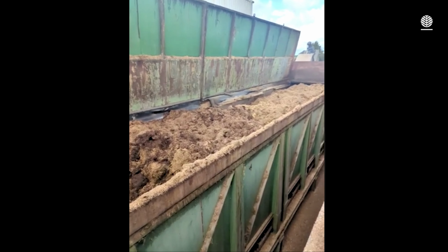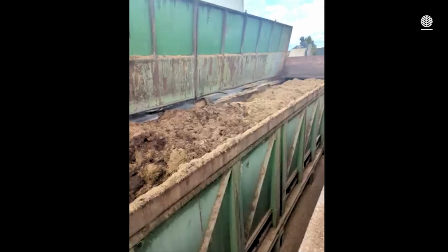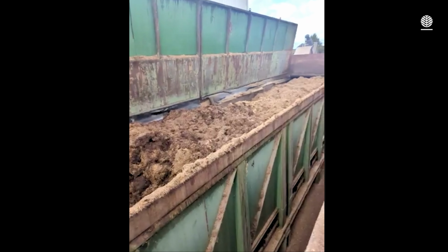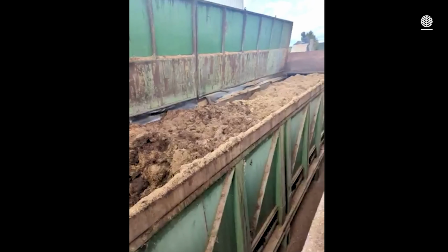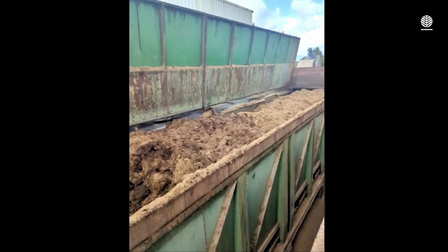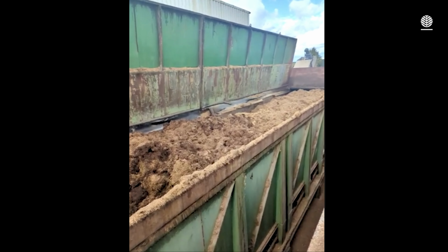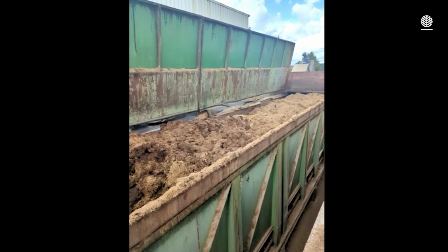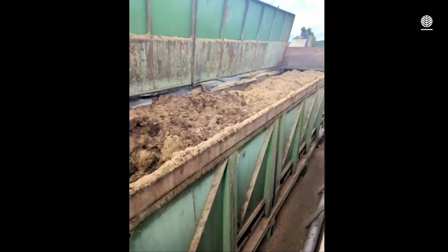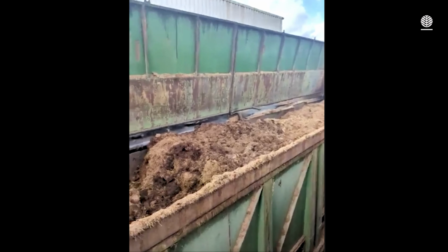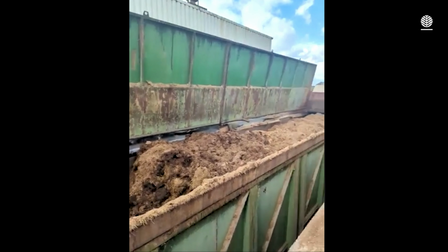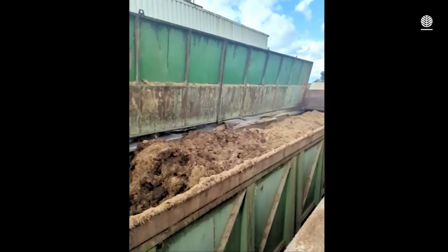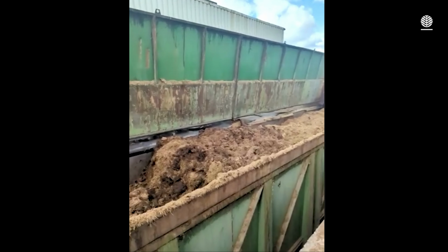Mr. Praveen, you have told us that you are pumping the material in the digester, but they are showing some screw conveyor there. So the pumping basically, this is a little bit older version. As Rückert told, this is a 20-year-old site. So the recent versions, what they are doing is to remove the stones. We are washing it. We keep a small 50-meter cube where the overflow comes inside, and then it pumps. So that's a recent advancement which we are adopting for the new projects.